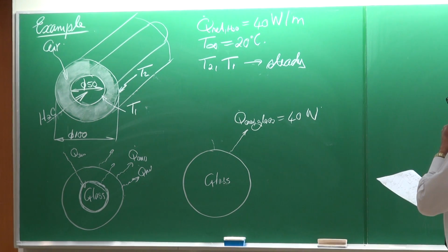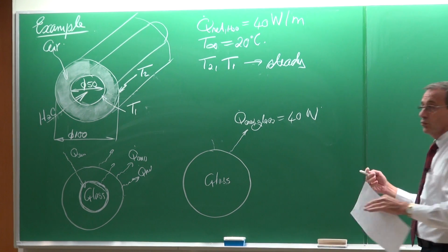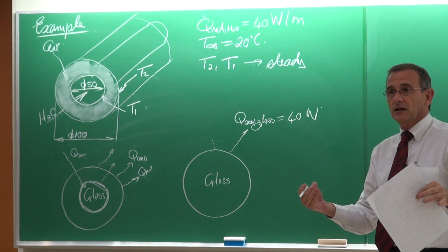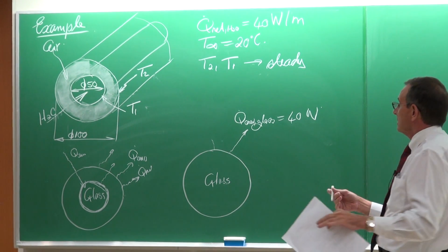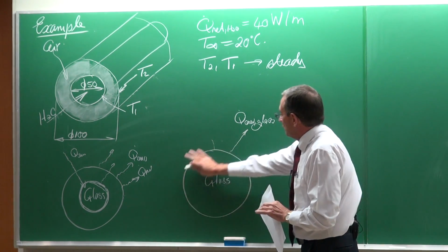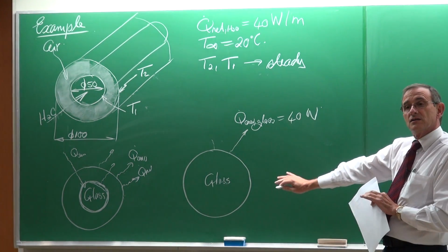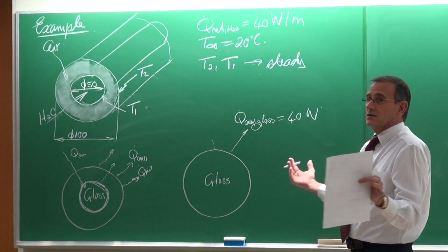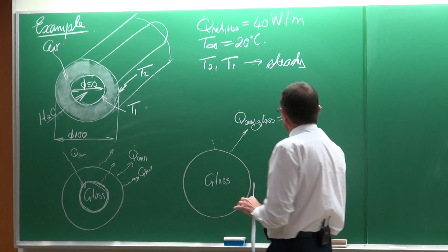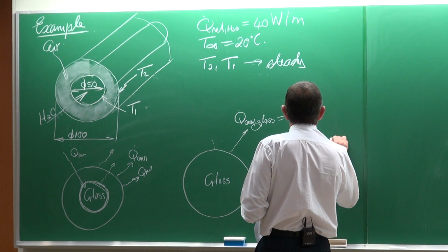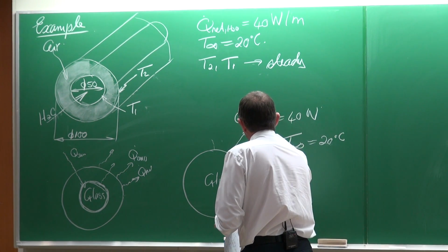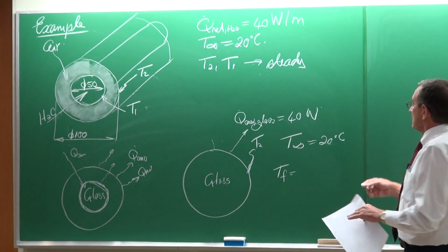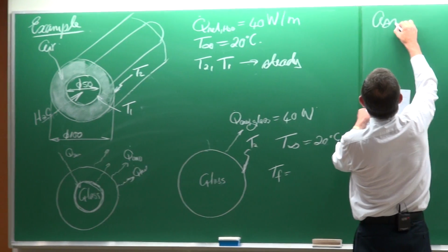So, now the thing is, if we think of the Grashof numbers and everything that we should calculate, we know that the properties are important. Okay, now the properties that we're going to have here for the natural convection is that of air. So we need the properties of air at a temperature. So the question is now, well, we don't have that temperature. Okay. That is the environment temperature, which is 20, and that is the temperature T2. So we have to go and get a film temperature.